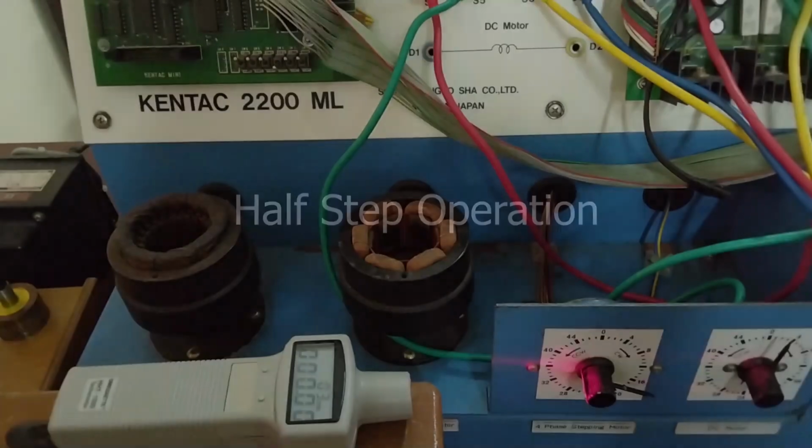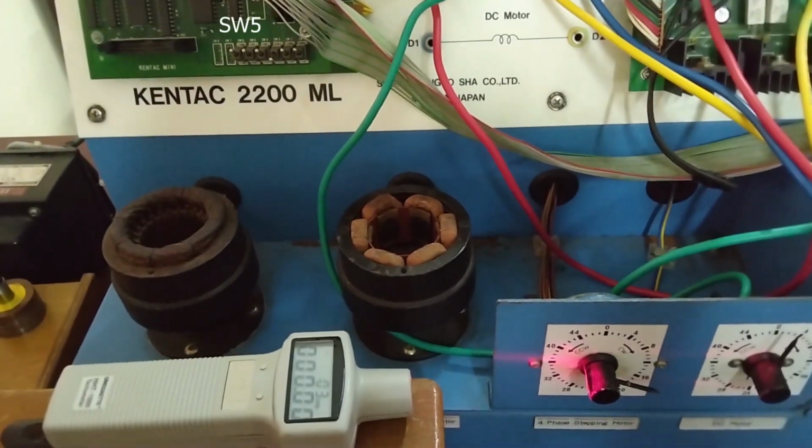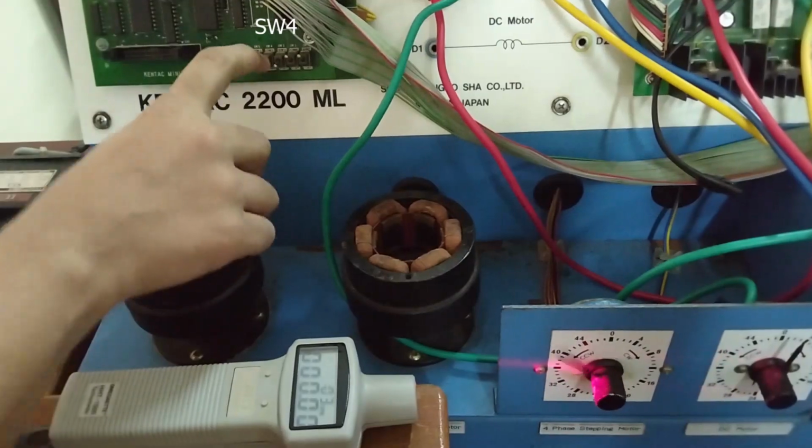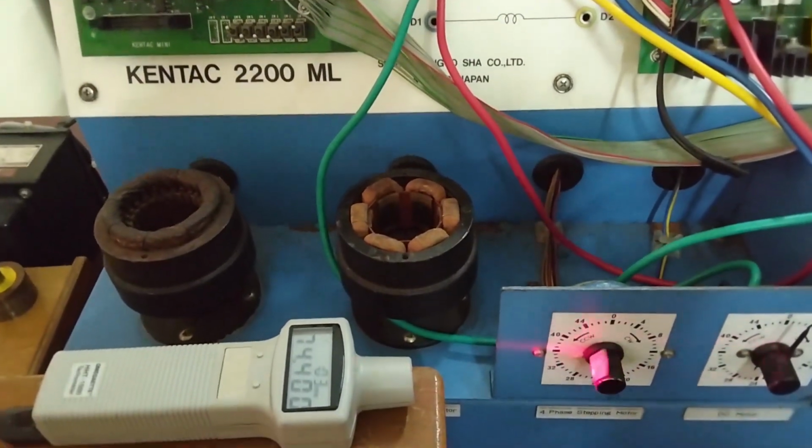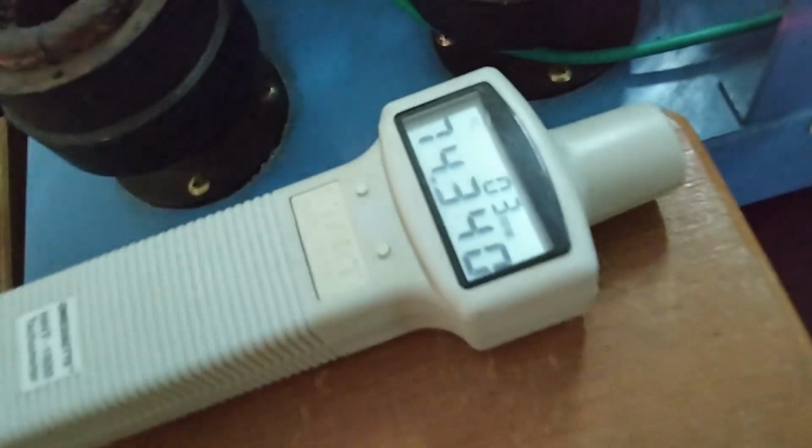Now, let's consider the half-step operation. To obtain this mode of operation, flip down the switches SW4 and SW5 on the microprocessor board. Let's measure the speed of rotation of the stepper motor and record its value too.